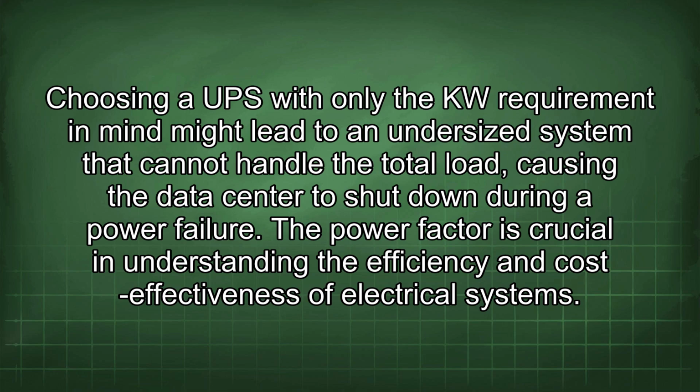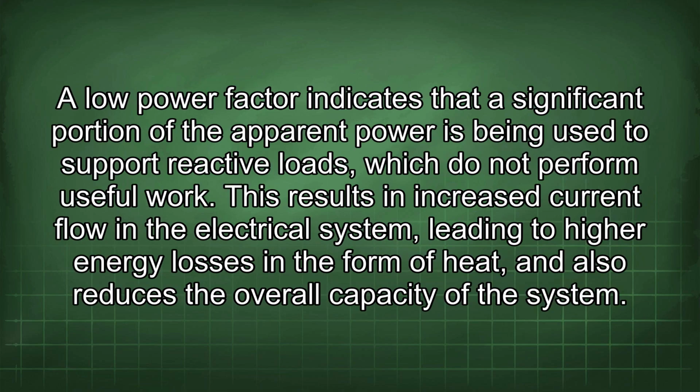The power factor is crucial in understanding the efficiency and cost-effectiveness of electrical systems. A low power factor indicates that a significant portion of the apparent power is being used to support reactive loads, which do not perform useful work. This results in increased current flow in the electrical system, leading to higher energy losses in the form of heat, and also reduces the overall capacity of the system.